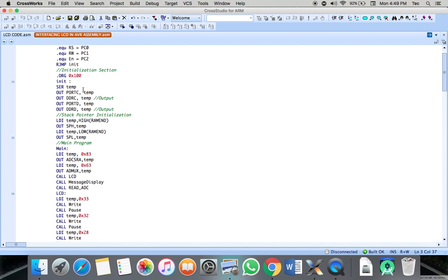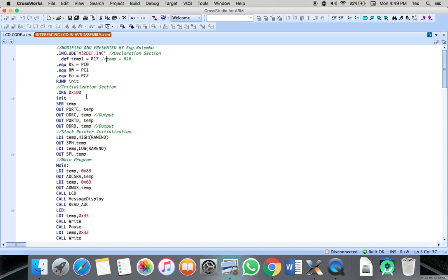When you say .org, what you mean is just begin from this particular address, 0x100, like that. Then we come to the label init. You see that we are setting the register temp to be high, and then we say out.